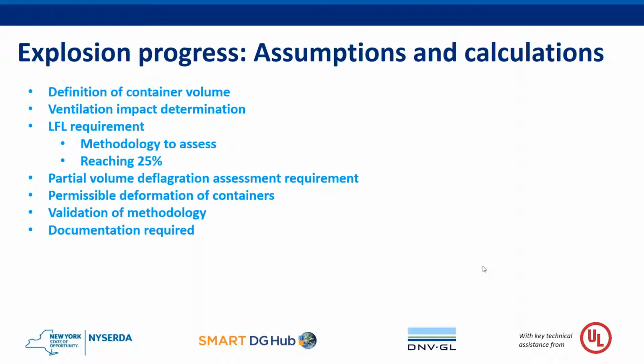On LFL, we talked about two distinct items. One is how do you assess and determine what the LFL is? The answer is that you have to determine it through testing, and it's defined in UL 9540A, the methodology by which that test is conducted. It's recognized that you can determine LFL through calculation, but that's not the methodology that we are recommending or planning to move forward with.